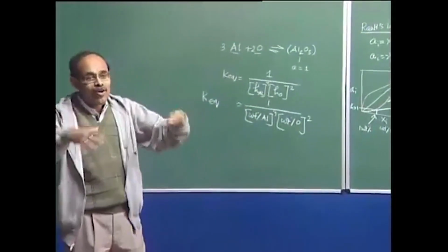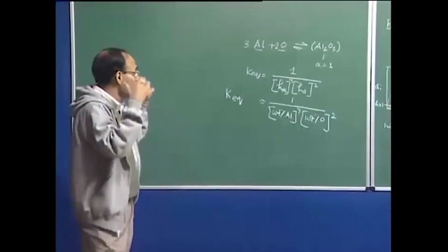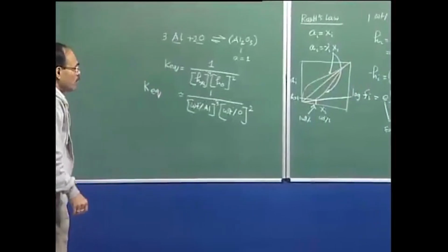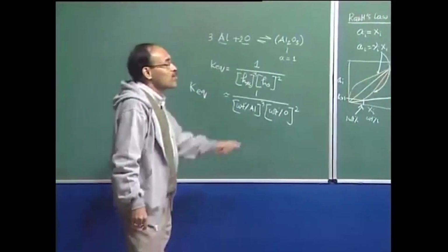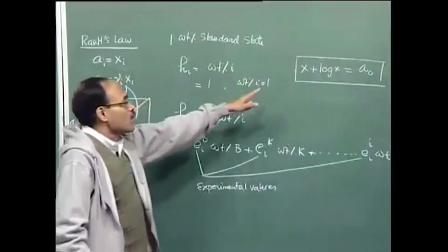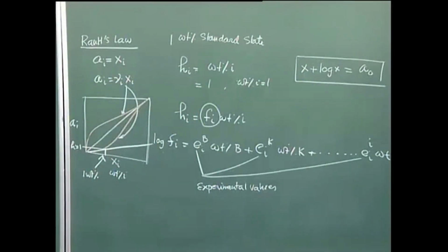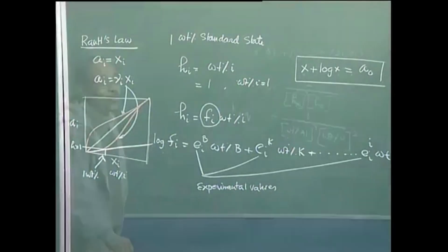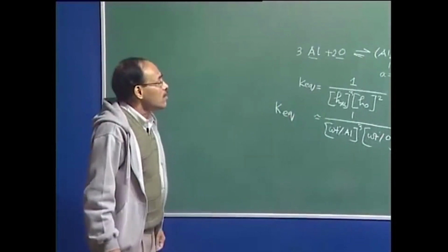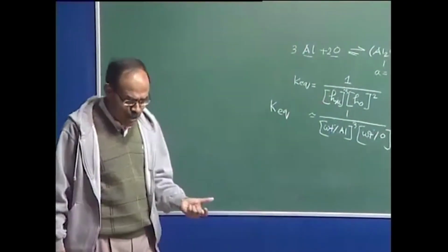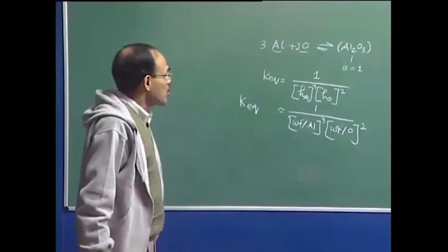We have to take into account manganese concentration, sulfur concentration, silicon concentration, and as a result we will require computational routines to solve, because we generate equations of this particular form which one cannot really solve by analytical means. So therefore, today we have to have large computer routines in order to calculate the state of equilibrium, give us the composition, the phases, concentration, etc.